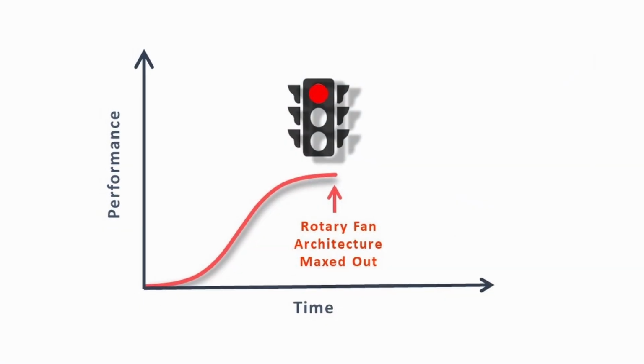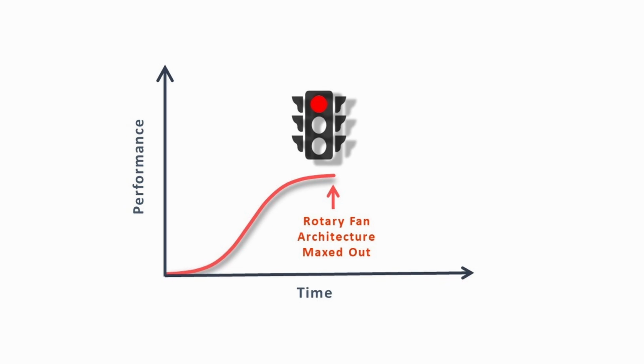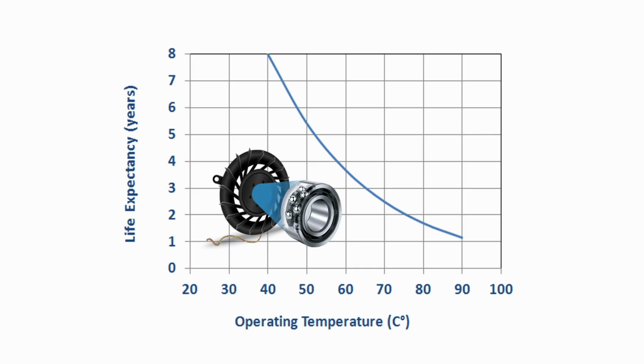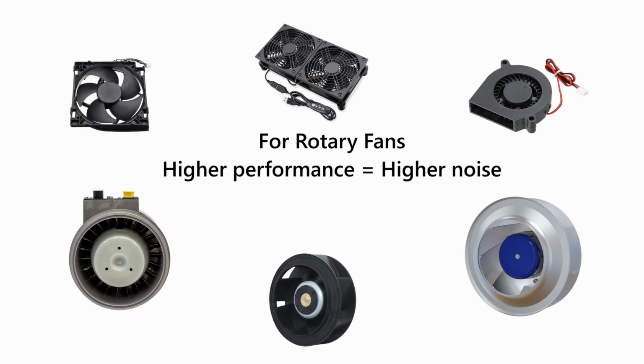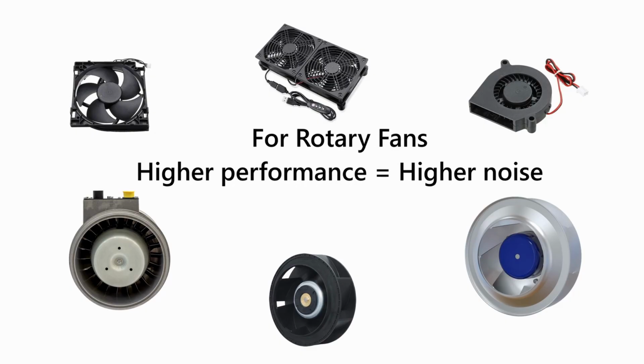But rotary fans have reached the top of their S-curve and cannot meet these conflicting requirements. Rotary fan bearings fail faster in outdoor conditions, where life expectancy decreases exponentially with temperature, which accelerates evaporation of bearing lubricants. Also, rotary fans must increase their speed in order to increase air performance, which results in more noise.